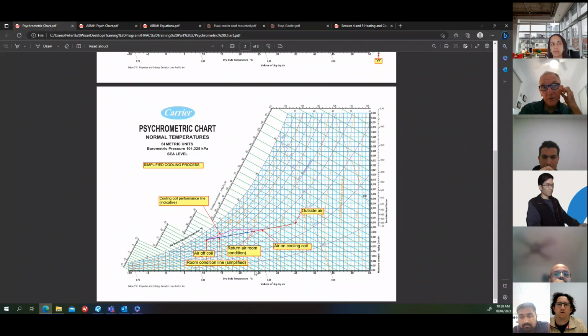Again, I'm going to simplify this because it's a bit more complicated than this, but you've got the delta T for the sensible heat in the room. And the equation for sensible heat is 1.2 times delta T times litres per second, as I said before. So from that difference, and you know what the room sensible heat is, okay?